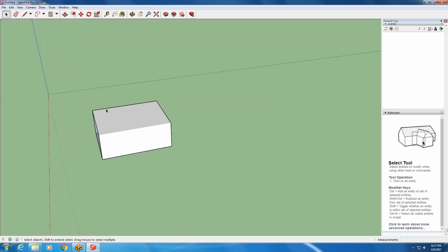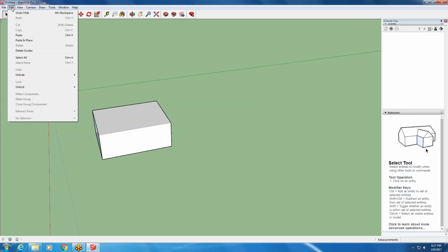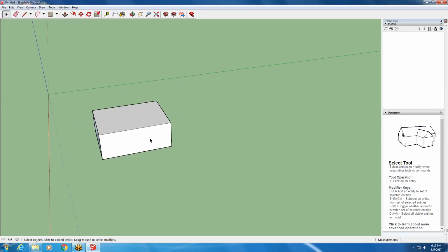I don't have to look at that dark outline. Now if I go to view hidden geometry, it'll show me which lines I've hidden compared to which lines are still solid, and notice it's denoted with a dashed line for hidden. So right now I'm going to edit, undo, hide because I want to keep my edge there for teaching purposes.